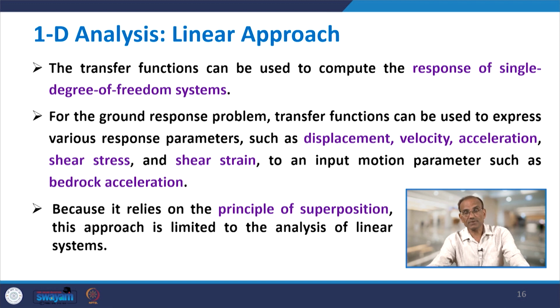For the ground response problem, transfer functions can be used to express various response parameters such as displacement, velocity, acceleration, shear stress and shear strain, to an input motion parameter such as bedrock acceleration. So, input is your bedrock acceleration and output could be displacement, velocity, acceleration or shear stress.